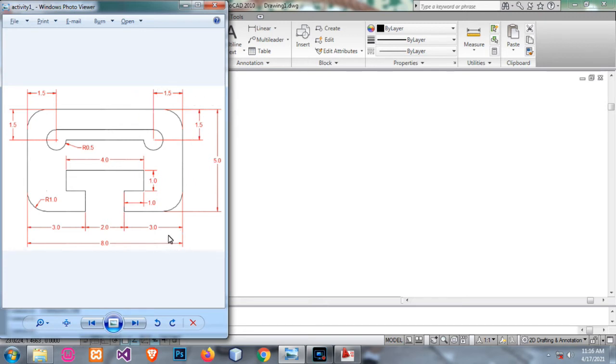Assume we are going to create a maximum x-axis of 15 centimeters. Meaning, if we set the units to 15, then 15 AutoCAD units is equivalent to 15 centimeters. And for your y-axis, we'll set it to 12 AutoCAD units, which is also equal to 12 centimeters, because centimeter is the default scale that we set in our drawing units. So now let's try to set the drawing limits.